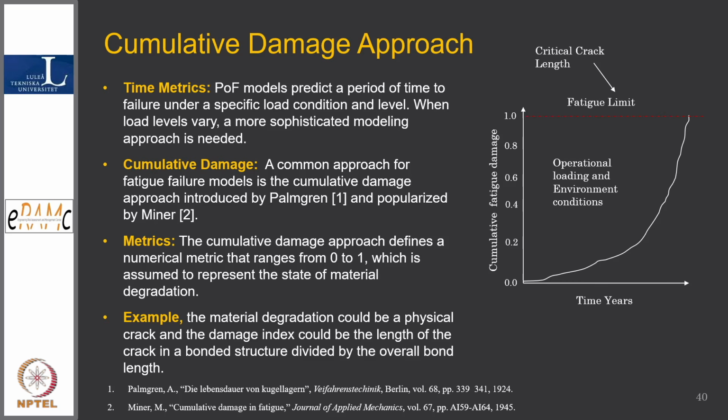Now you see, the cumulative damage approach is applicable in all fields, but especially for fatigue fracture. This is because a crack develops and slowly grows, and when it reaches the critical crack length, then the limit comes. It comes in the number of cycles range, but physically the crack can go supercritical after that. So one adequate margin is required, and we can say this is our limit.